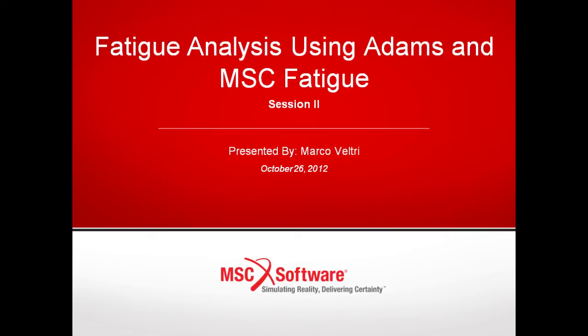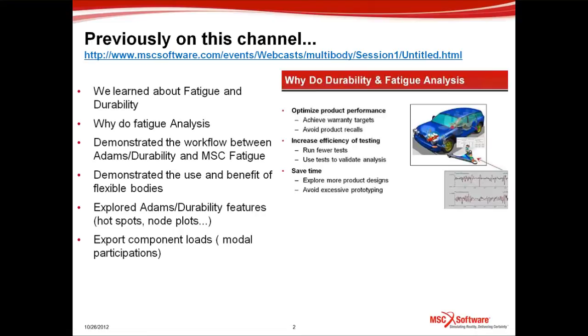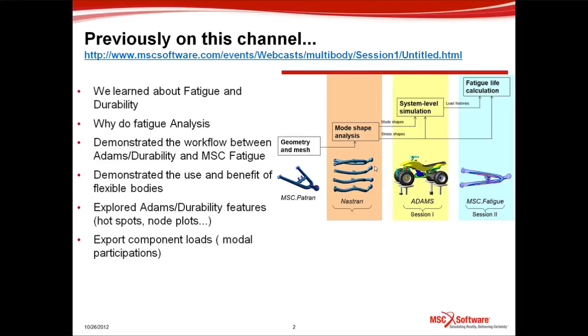I will be continuing on the work that was presented by my colleague in the previous session, as demonstrated the workflow for a durability analysis with dynamic loading obtained via Adams. In fact, we learned about fatigue and durability while doing fatigue analysis, and we demonstrated this process of going from a finite element to produce a flexible part that can then be accessed by the multi-body dynamic system. And then we stopped right short of passing the information with regard to the loads to the fatigue code, which is what we're going to be doing tonight.